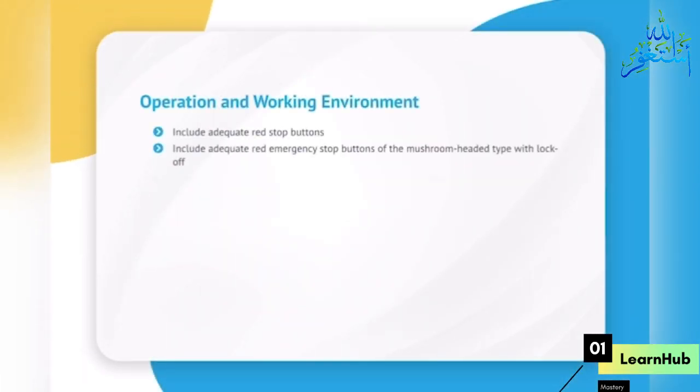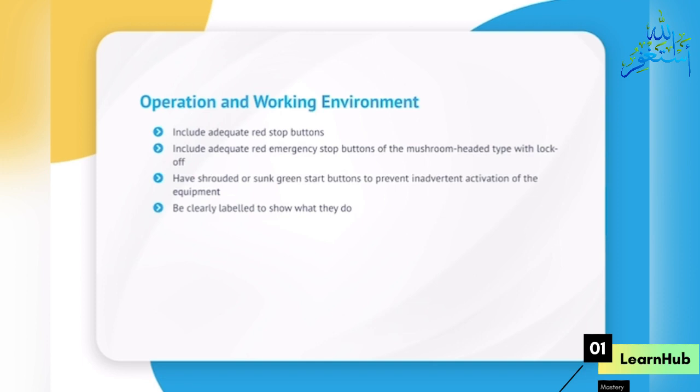Include adequate red stop buttons. Include adequate red emergency stop buttons of the mushroom-headed type with lock-off. Have shrouded or sunk green start buttons to prevent inadvertent activation of the equipment. Be clearly labeled to show what they do.